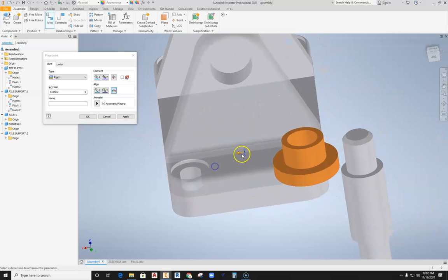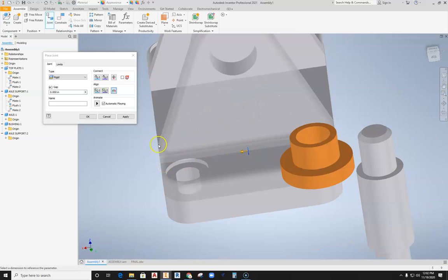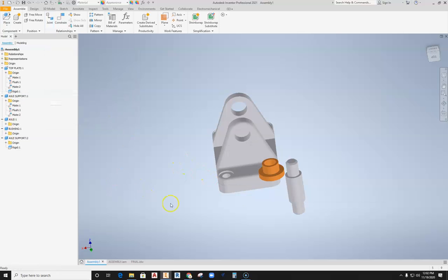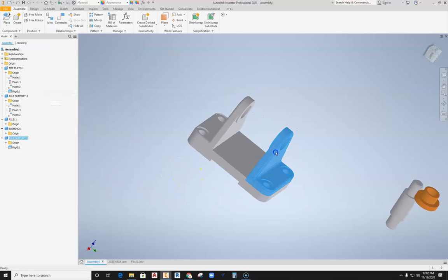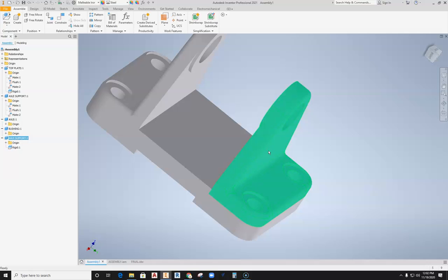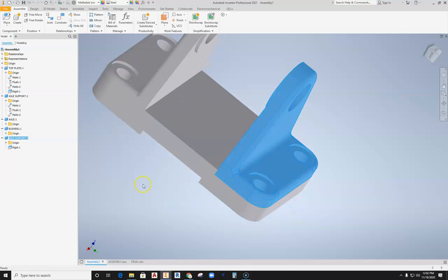These two coming together like this aligned everything, because I basically put center of part and center of base together. I'll hit apply, cancel, and when I go to move one of these apart, I was able to accomplish in one joint what I did in 3 constraints over here, because it includes multiple constraints, or multiple removal of degrees of freedom, with that part.